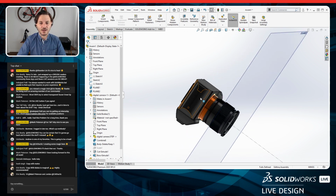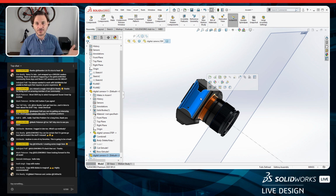So if I click on any face of any part in an assembly, or even when editing a part, you'll notice this new little user interface up here. This is called Breadcrumbs. What it really shows me is the entire history of how that part, or in this case, this face, came to be. What part is it part of? What features were used to create this face, et cetera.